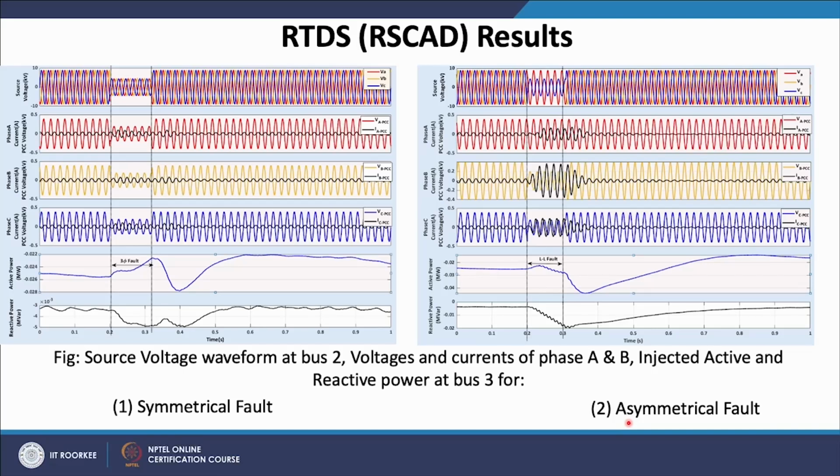In order to test the behavior of the DFIG wind system at the most severe unbalanced voltage, the phase-to-phase asymmetrical fault is considered in the analysis, as the phase-to-phase fault results in a larger negative sequence component in the voltage than the single-phase fault for the same depth.